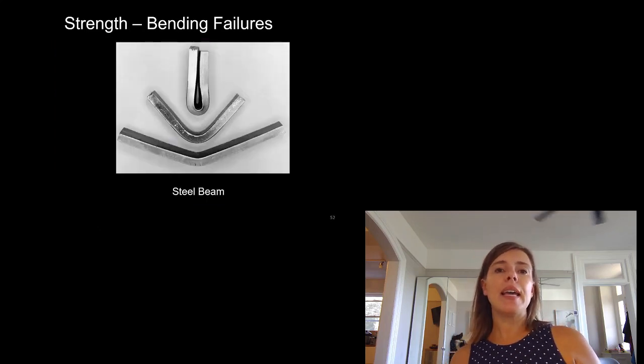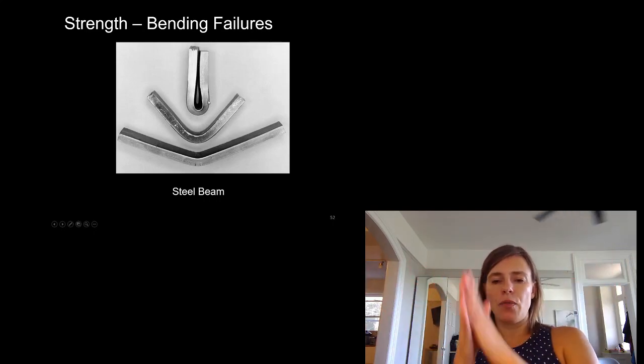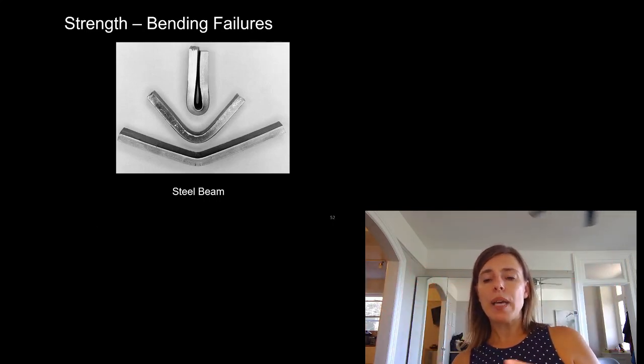Here is a steel plate bending. You can see something interesting here. It gets a few cracks here, but it doesn't actually seem to fail apart. It eventually starts to bend more and more and more until it folds up on itself. That's because we have a few things happening here. We started with a bending failure, where we could see here. Then it started to yield, which is something we're going to talk about going forward.